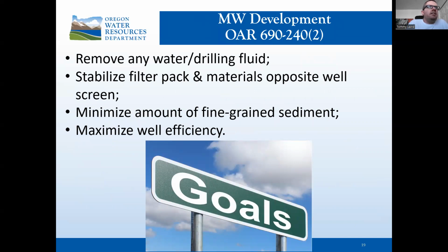Continuing on, you must remove any water or drilling fluid. You have to stabilize filter pack and materials opposite the well screen, minimize the amount of fine-grained sediment, and maximize well efficiency. This is the function of well development, essentially.